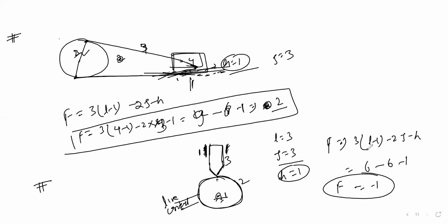just a minute. Okay, here the joint is only 2. One joint is here and one is here. The joint is only 2. So 2 is a 4. 4 plus 1 is 5. 6 minus 5 is 1 here. So the degree of freedom I am getting here is 1. It means this is the mechanism. This is the mechanism.